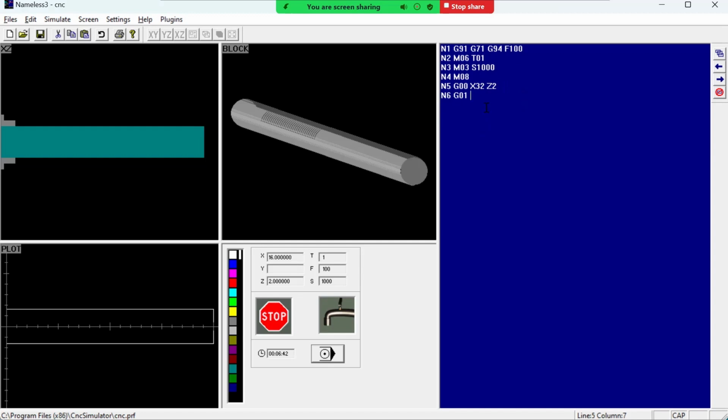So in the incremental coordinate system, we need not go with a fixed origin position. So for the next line of code, the system will take this point as an origin. So this point is somewhere here. So this will be taken as the origin, and the top will be plus x, bottom minus x, plus z, minus z. So we need to move the tooltip below. So this will be minus x, and we are required to specify the distance by which we need to move it.